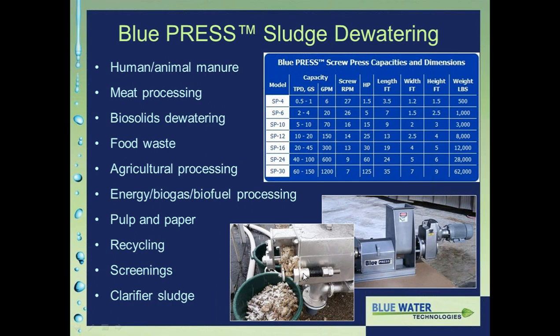We have these integrated with the EcoMat rotating belt filter systems, either mounted to the unit or in a centralized location where multiple cartridge modules can have their sludge pumped or conveyed to a dewatering system. And these will pretty consistently get between 30 and 40% dry solids on primary wastewater or primary sludge and screenings scenarios such as the ones listed on this sheet.